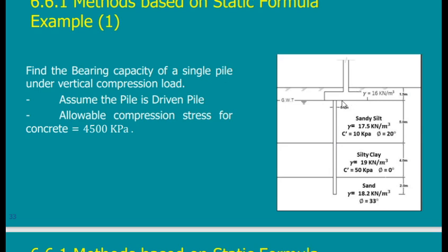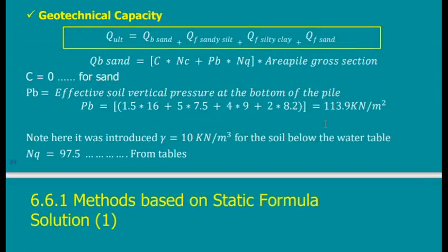The middle of the layer is from the start of the pile to the end of the layer. This is the middle of the layer. So it is at this point. What is the depth of this point? It is from here to there, which is 5 divided by 2, plus 1.5. So 1.5 is not included in any middle. It is just an additional load on the pile. This is the only difference that we will do here.